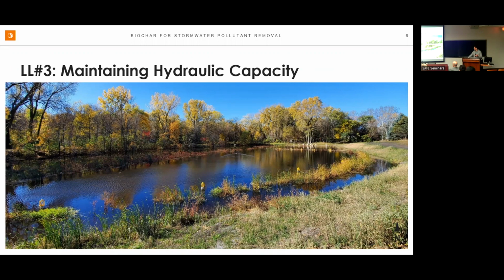And then the second part of that is, even when we install it, it needs to be maintained with the iron enhanced sand. It needs to be tilled. You need to break that top layer. And the biochar does break down. So even if you do get a biochar that fits your gradation perfectly, you have the right uniformity coefficient that you're looking for, over time, it's going to break down. So you're still going to have fines.